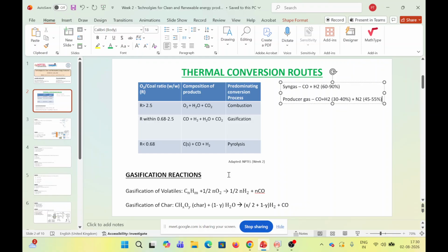Next is your gasification agent. By gasification agent, we mean whether we use oxygen or steam. Then we go for the type of heating. Gasification is not just conventionally increasing the temperature; there are also modern techniques like plasma gasification, where we use plasma to generate heat, and that burns the coal and produces the syngas.